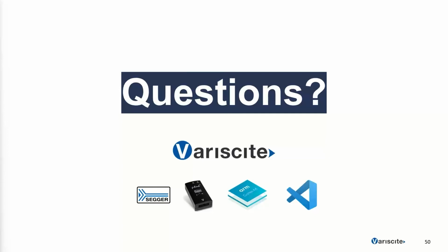If you're using a GPIO pin, the one thing to know is that you should disable the entire GPIO bus on the Linux side. So when you're designing your hardware, you should allocate the GPIO pins in a way such that the ones you want to use from Linux are on one bus and the Cortex-M firmware on another bus.